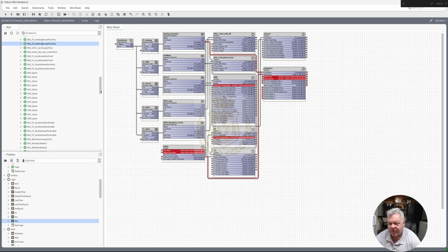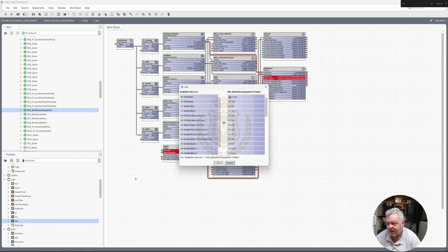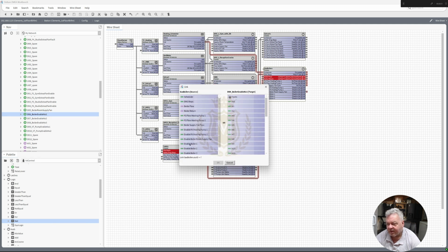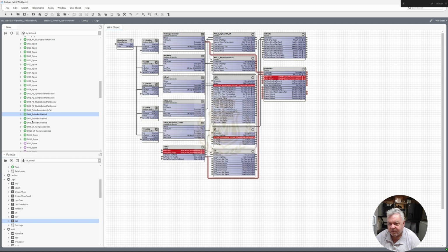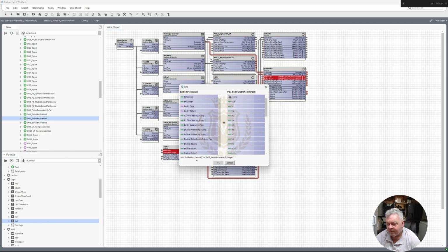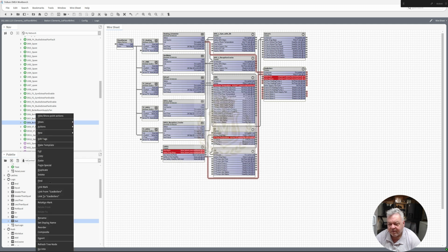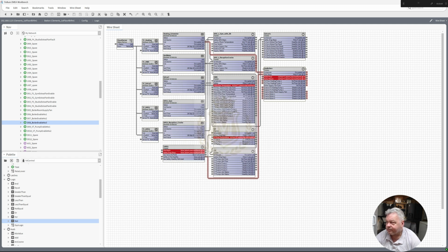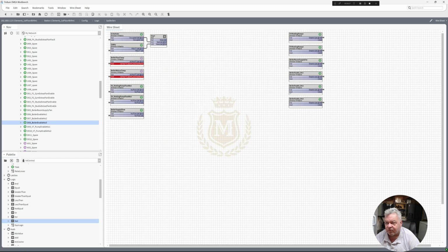Boiler supply fan we're not going to see because we don't have the point for it, but link from for the output to enable it is there. Link from gas boilers, enable 1 to there. Link from 2 to there. Link from 3 to there. Right, so that's them all linked. We've just got to write the logic.